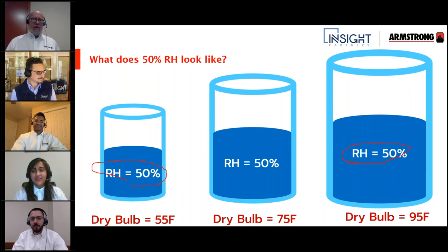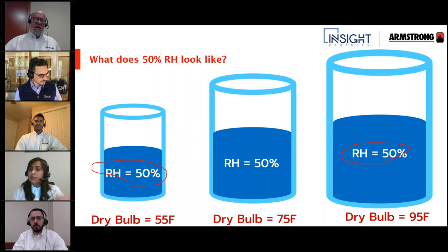So there's two different types of sensors out on the market. There's a capacitive sensor and then there's a resistive sensor. Depending on which one you're using, they have a conductive film on them that is moisture sensitive, and it absorbs and gives up its moisture. As you pass a current or a voltage across that sensor, the change in voltage or the change in resistance, depending on whether it's a capacitive or resistive sensor, has a chart that it compares it to, and it says, okay, at this change in voltage, this is what the resultant relative humidity is.